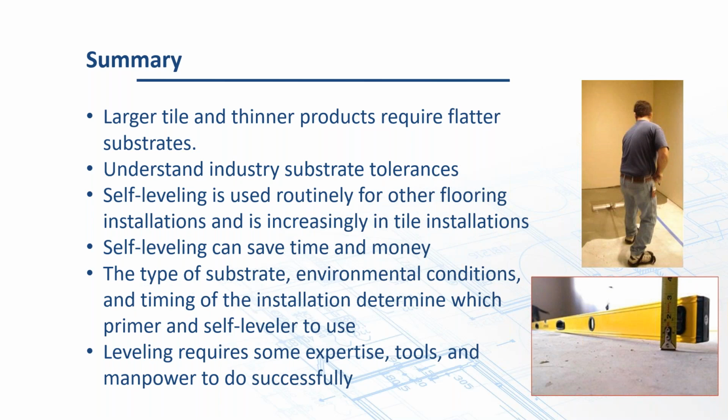Self-leveling can save a lot of time and money on the appropriate project. The type of substrate, environmental conditions, and timing can determine the leveler and the primer that you're going to use. But leveling does require some expertise, some tools and manpower to do it successfully. Without those, you're going to probably have a big failure.